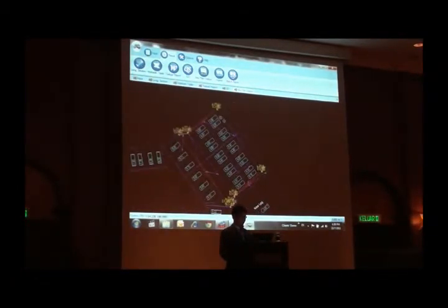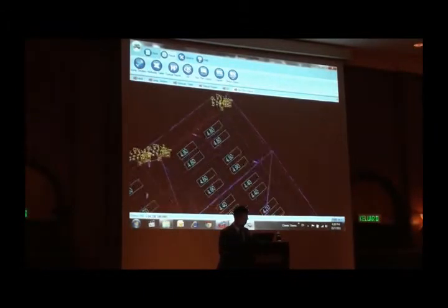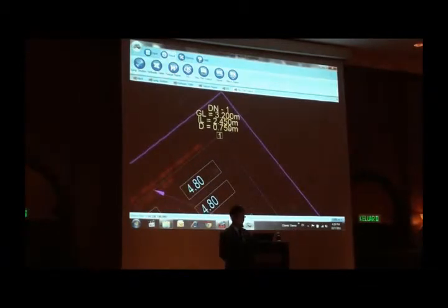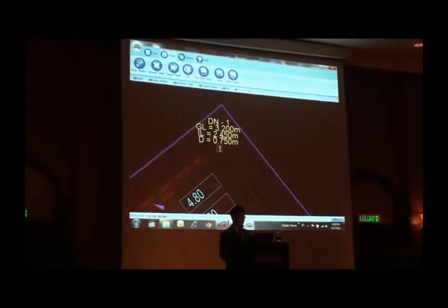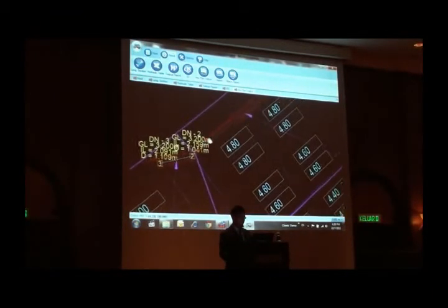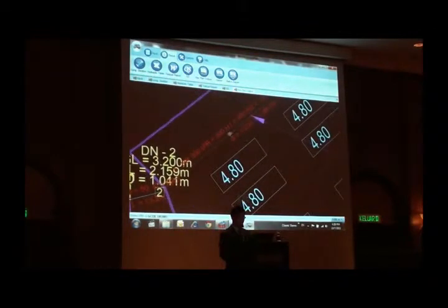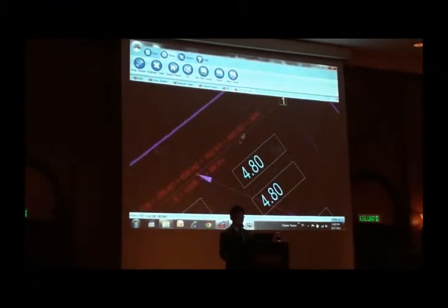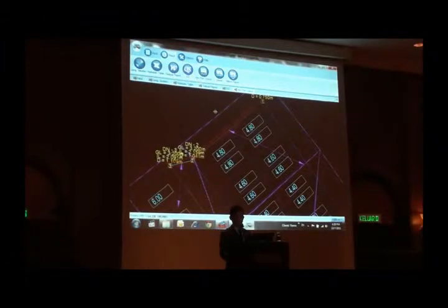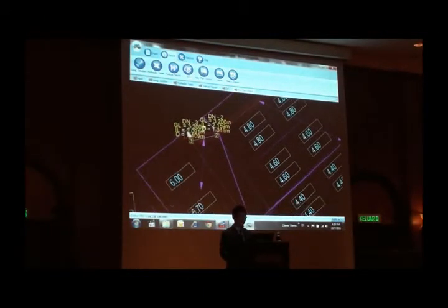Okay, so this is the output, the key plan output. You can see the drain number 1, ground level, invert level, and the tap will be drawn automatically for us. Then we have this half round 300, freeboard, H1, H2, W1, W2. We can always turn on or off. If you don't need the value, we can turn off the text we don't need in the parameter setting, or after you export to AutoCAD, you can move or edit it in AutoCAD.